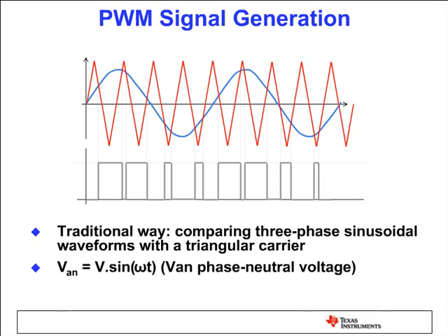And although the combination of pulses looks meaningless, when we low pass filter the pulses, we will see the fundamental component, like the blue vector here, the sinusoidal vector, which is a voltage waveform and low pass filter form of the pulses. Now there are a few different types of PWM generation.